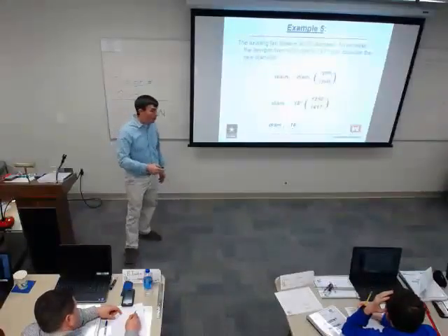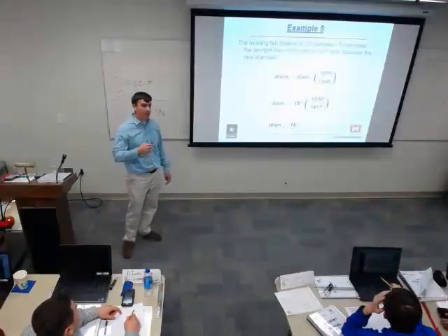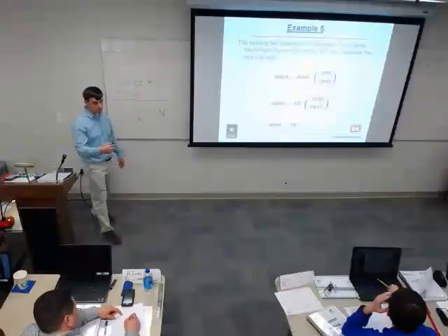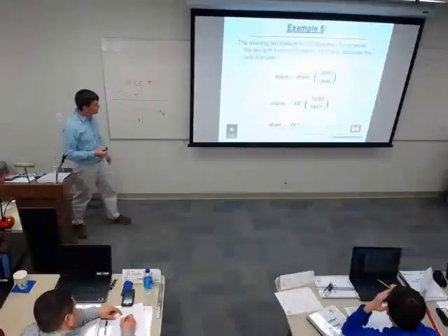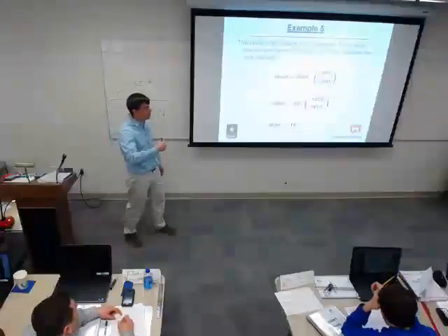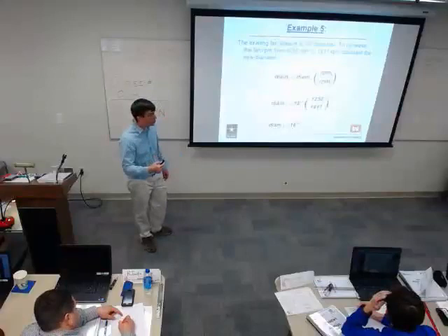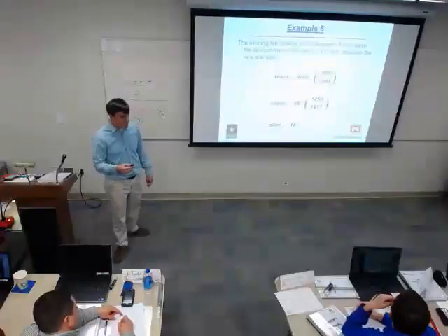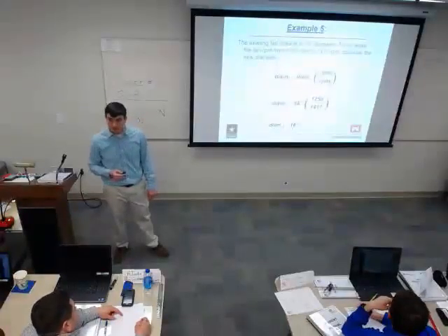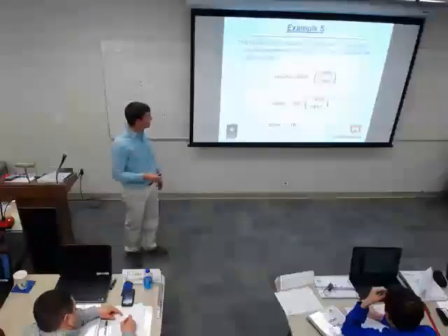Sheave size went down. Okay, so I'm changing the fan sheave. All right, does that make sense? I want my fan to spin more, so I got to put a smaller sheave on it. I'm not changing my motor sheave, I'm changing my fan sheave. Are we okay with that? All right.